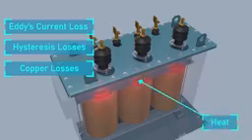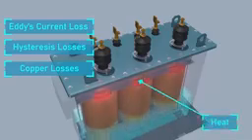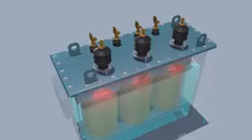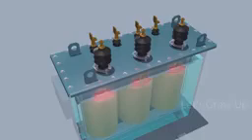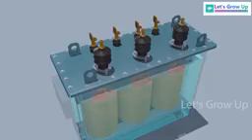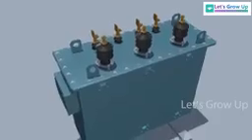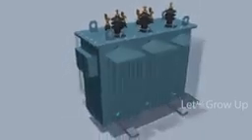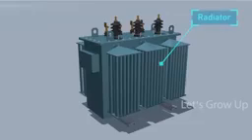To prevent heat, transformer oil is used inside the tank. The main role of transformer oil is to act as a coolant and to insulate. Transformer oil is an exceptional heat conductor, and can effectively reduce the copper coil's temperature, stopping them from burning. Not only that, external cooling tubes, or radiators, are there. The radiator of the transformer accelerates the cooling rate, thus it plays a key role to increase the loading capacity of an electrical transformer.